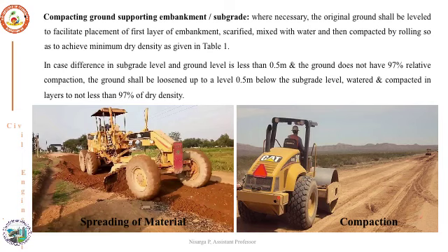Then the compacting of the existing ground must be done wherever it is necessary. First the layer has to be leveled and then compacted. Here you have to note that, if required, water has to be spread to achieve the OMC condition, and compaction will be done such that you achieve maximum dry density.